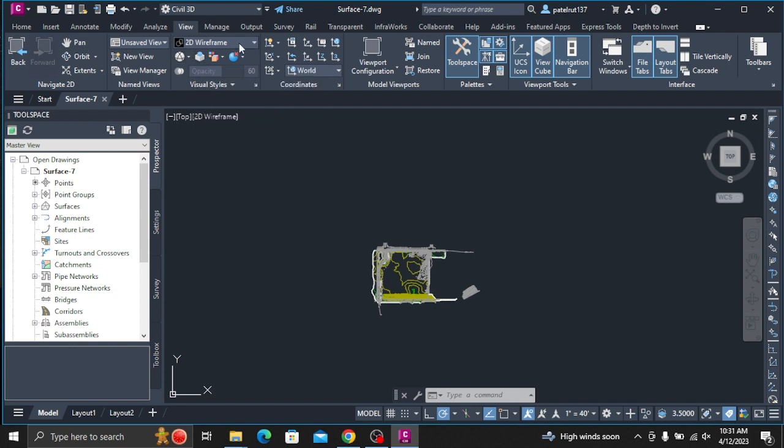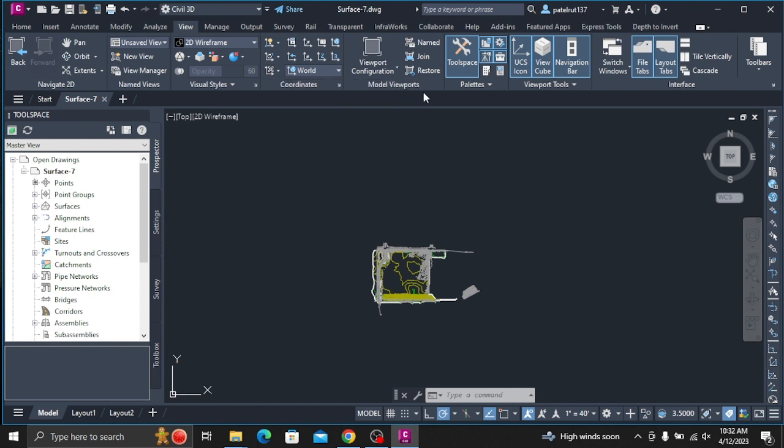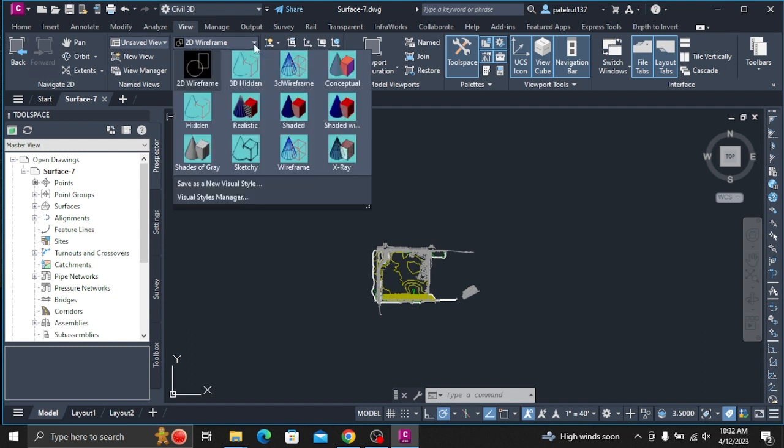Click View tab, Views panel, Views list, 3D detail. In the 3D view, notice that the street light block appears at the lower portion of the drawing and is not at the appropriate surface elevation. In the following steps, you will move both blocks onto the surface.